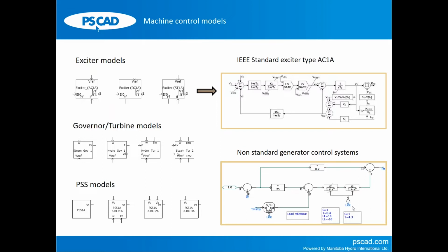If you don't back initialize these custom models yourself, it might take a while before these controllers bring the output to the expected steady state, and you might have to run the simulation for a little bit longer to get it to the stable operating point. There is also always a danger that it will never reach the steady point.